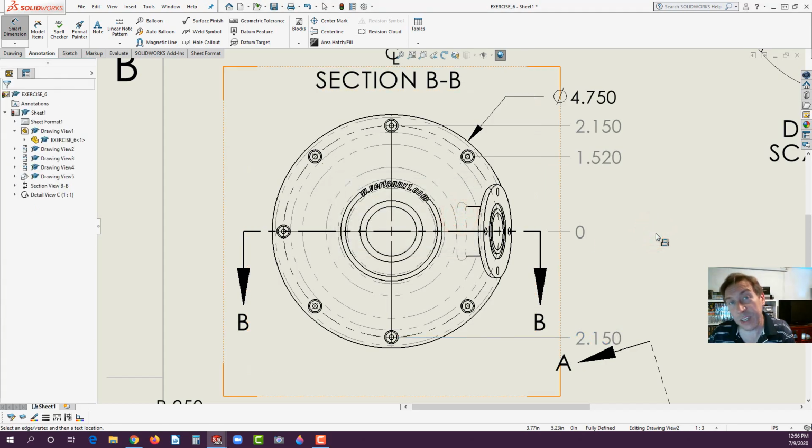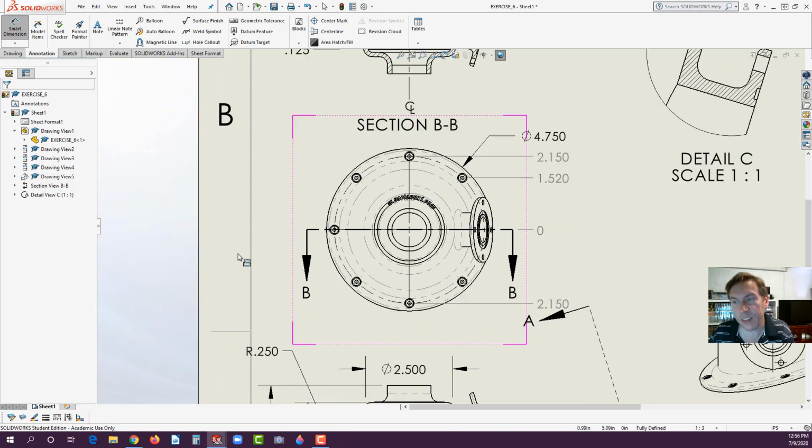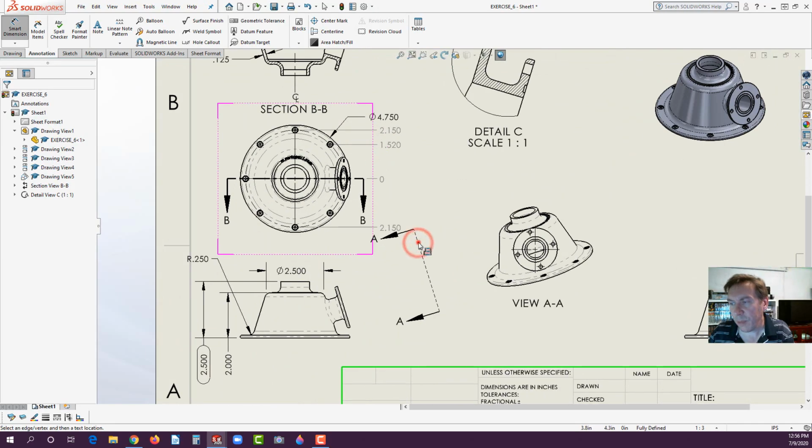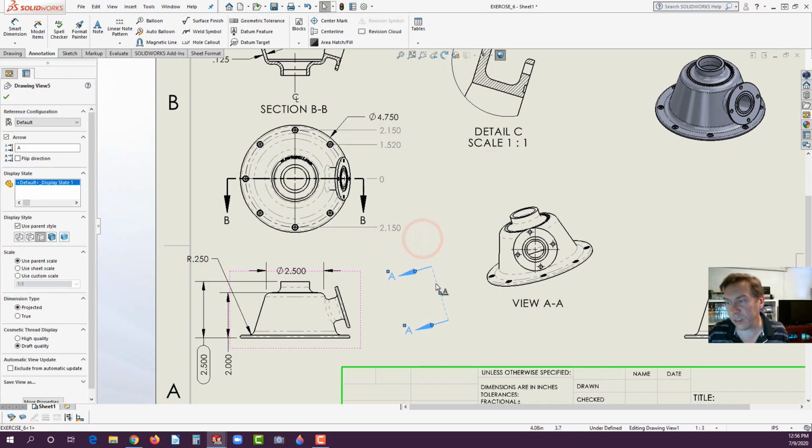Now, when it says it's a driven dimension, that means its value can't be changed, and we can see that by the color. Now, if you don't want that to print out grayscale like that as a reference dimension, when you go to File, Print, you can specify just black and white versus grayscale for the print, and thus those will all come out the same color. Now down here you do have a color display mode too, if you want to turn colors off and things like that. Okay, now these little arrows, let's hit Escape. You can move this and actually squeeze this down a little bit.